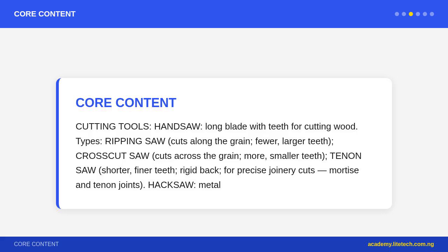Joining and assembly tools. Hammer, drives nails and taps chisels. Types: claw hammer, carpenter's hammer, drives and removes nails using the claw; ball peen hammer, engineer's or metalwork hammer, domed striking face plus hemispherical pin for riveting and metalwork; mallet, wooden or rubber head, used with chisels to avoid damaging the handle.